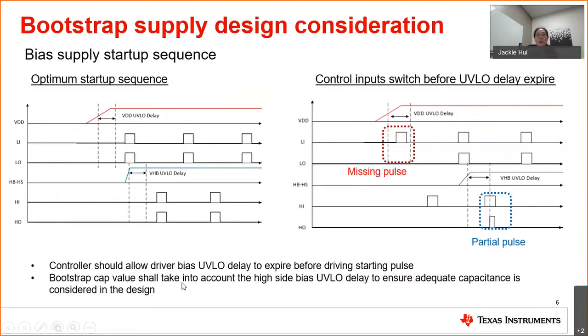Now, another thing when you are selecting the boot cap value: if the driver has a relatively long UVLO delay time, maybe in milliseconds, you want to make sure your boot cap value takes the UVLO delay into account. You want to make sure the voltage at the boot cap when you charge up will hold to a decent value, not only for the duration of your high side driver on period, but also during the UVLO delay as well.